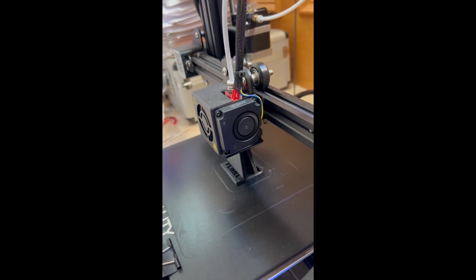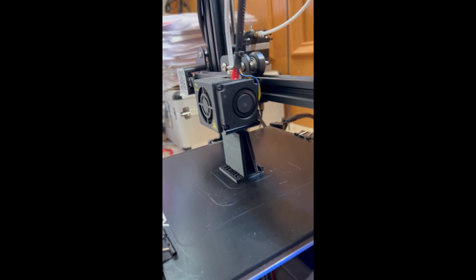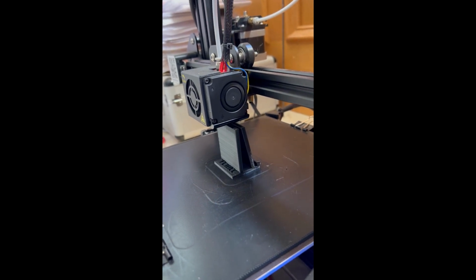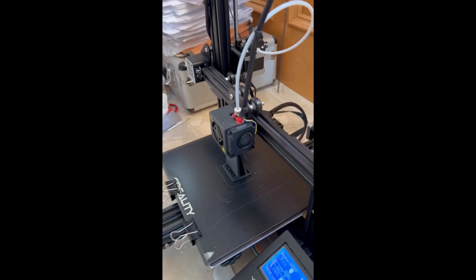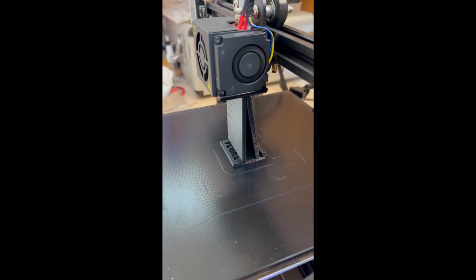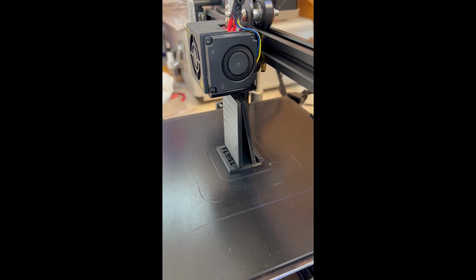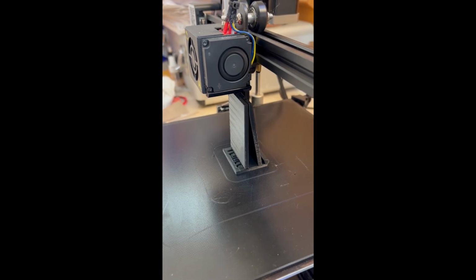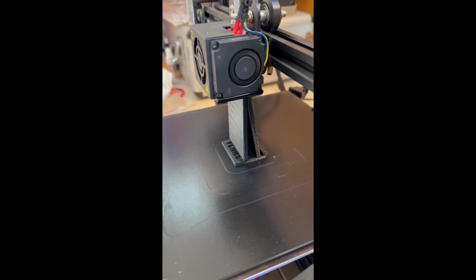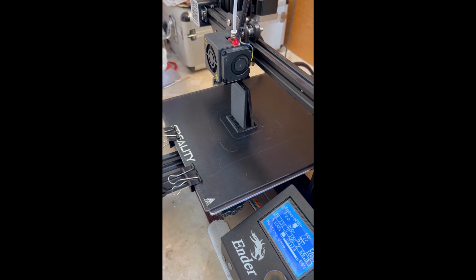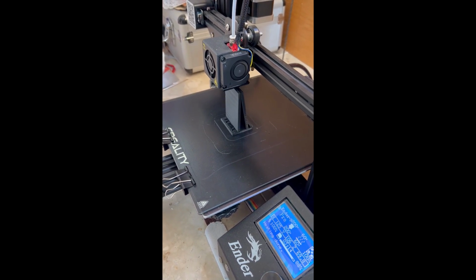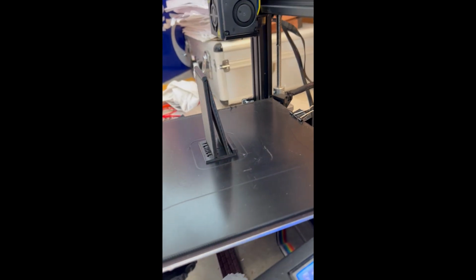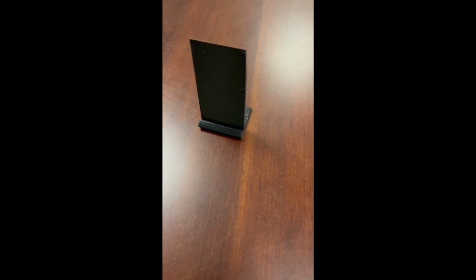So this 3D printer just prints in different dimensions, horizontal and vertical, on the X, Y, and Z axis. You don't really need to know all of that. The slicing program and the 3D printer take care of it all for you. But just keep in mind that it prints in all levels, up and down and forward and across. And that's kind of important when you're setting up your 3D printer. You want to make sure that your little build plate right there, your little printing plate, is very, very, very flat.